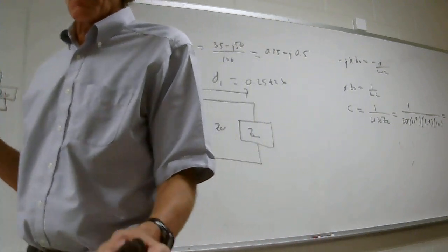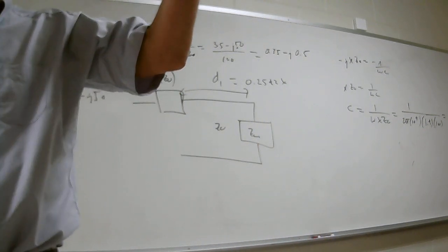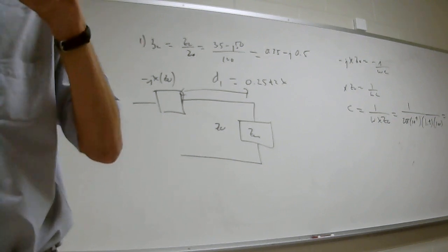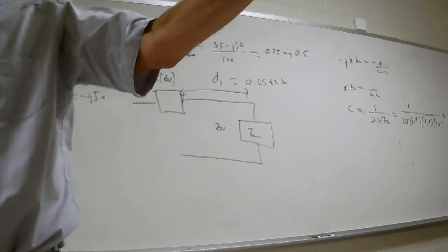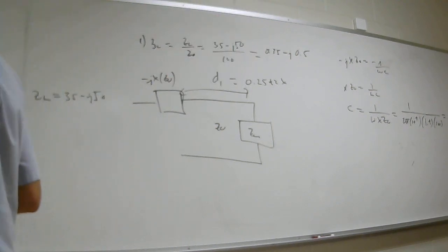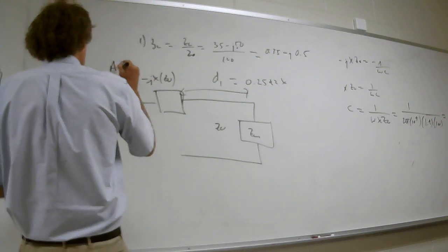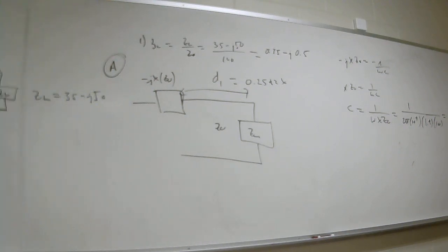Just everybody follow along on the reasoning behind this. To get a matched impedance, it means you have to look into Z naught, and you have to get rid of the reactive component. That means you have to travel from this point all the way until you intercept the one circle, and then you have to get rid of the impedance component, the J, or the reactive component. With me, class? That's the first part. I'll call this design A. It's using the capacitor. Now, if we want to use an inductor,